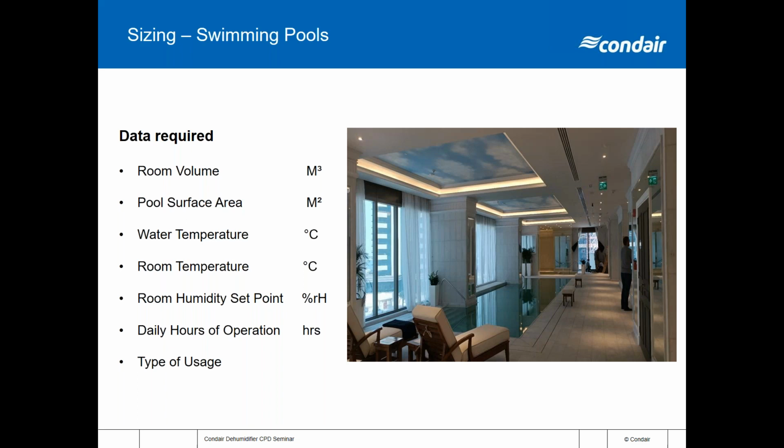And again, I mentioned earlier in the presentation, it makes a huge difference. If you've got a pool temperature of 35 degrees C and an air temperature of 15 degrees C, you'll get a huge amount of evaporation coming off that pool, and you need a huge dehumidifier to cope with it. As opposed to keeping the air temperature a couple of degrees above the pool temperature, which will dramatically reduce the evaporation that takes place from that pool, and again make your facility much more efficient.